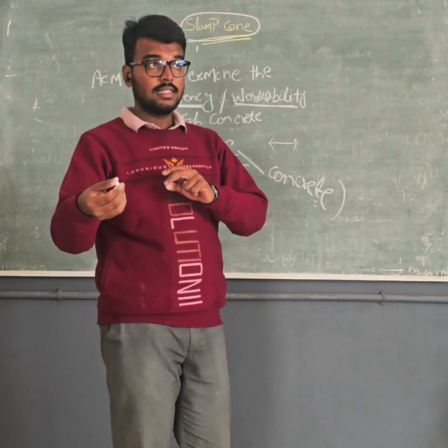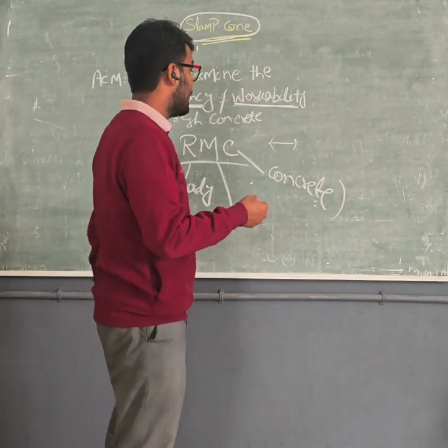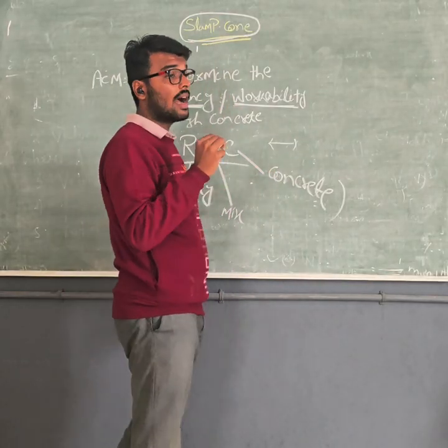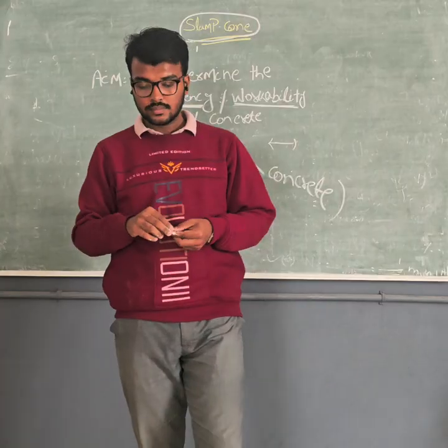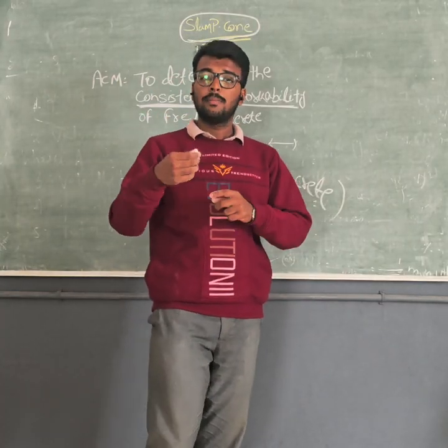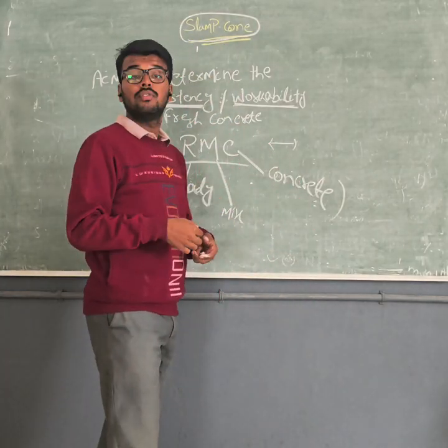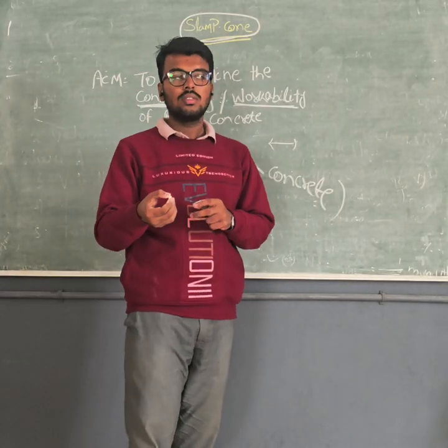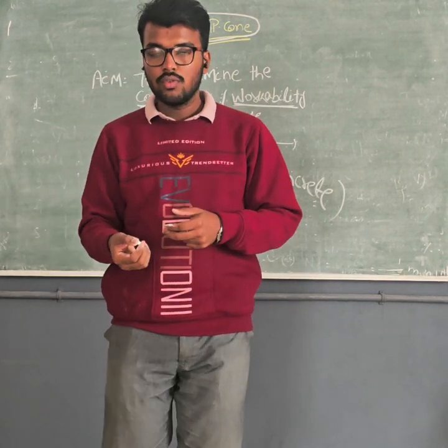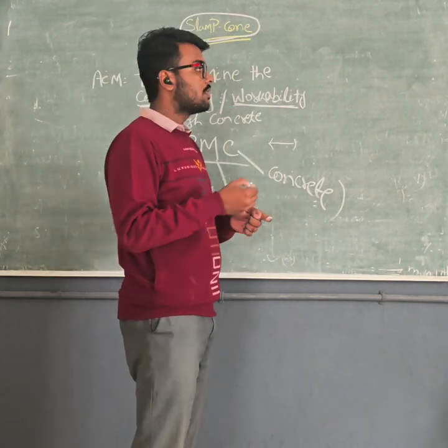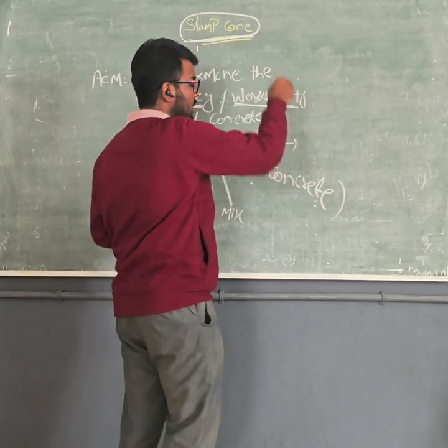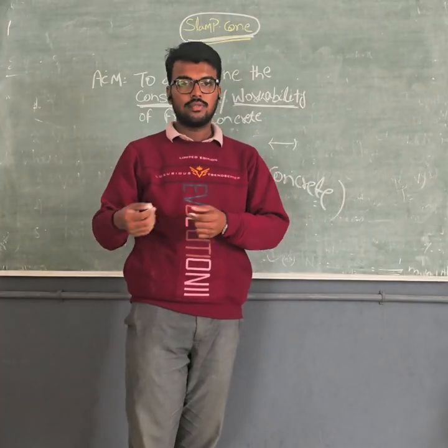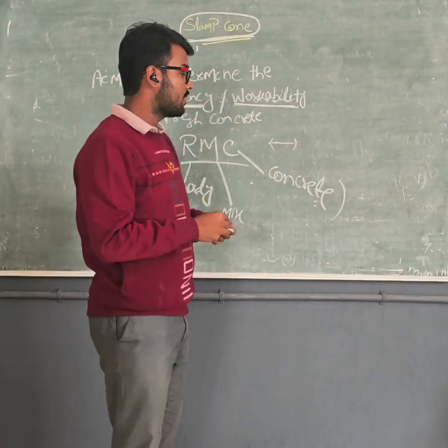After casting, if we see some segregation or bleeding, the concrete is not suitable for our site. So we do a pre-test to know whether the concrete is good or bad for our site, and we find that this concrete is for our site or that concrete is not.